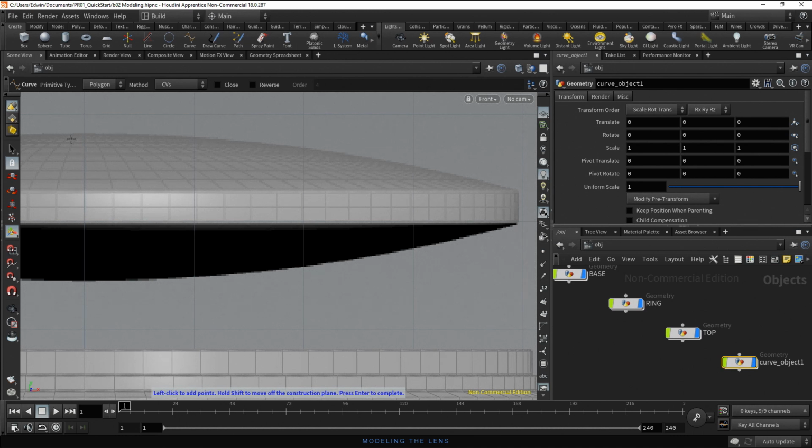Now you are ready to draw the curve points. You can draw polygonal lines, nurbs curves, Bezier curves, or points. Let's select the nurbs option. Start placing the points. And at the end, hit Enter to finish. To modify the point positions, just click on them and drag them.